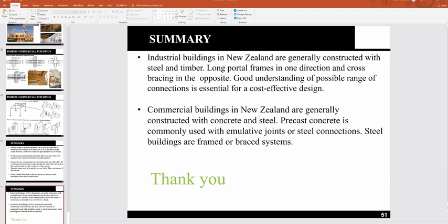What is base isolation, sir? Base isolation is like this: you have a structure, and rather than putting it directly onto the ground, you put it on a rubber pad. Rubber is so soft that your structure is not going to deform, the rubber pad is going to deform. So your rubber pad may fail, but your structure stays intact. Basically, the idea behind base isolation is that you don't transfer the forces from an earthquake or any shaking to your structure, so your structure stays as it is.